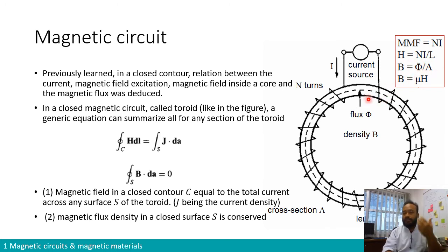So it's easier to think of a magnetic circuit in terms of flux. As we have seen together last time, the lines that we see in magnetism visualization are what we call field lines. Field lines can also be seen as the flux. So it is the circulation of that magnetic field, right? So flux in relation to magnetic field is basically: magnetic field B equals flux divided by the surface area in which the magnetic flux circulates.